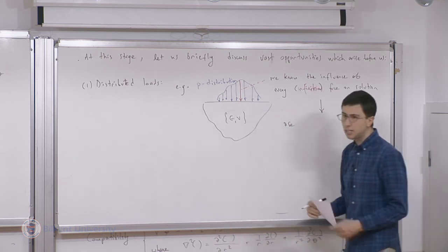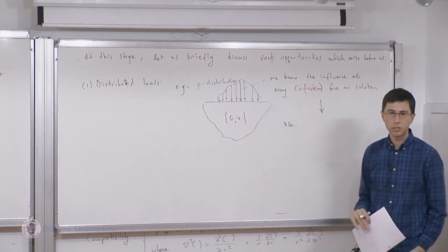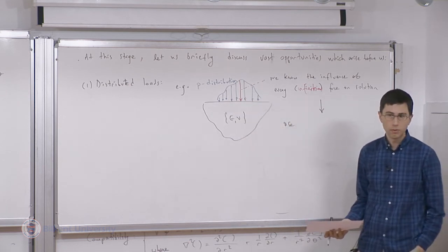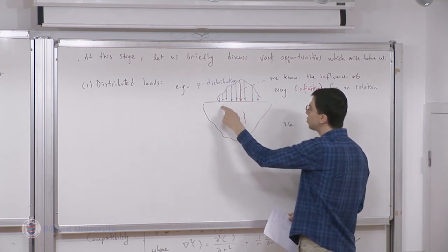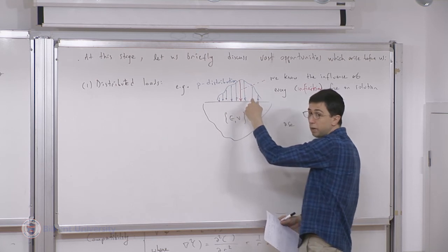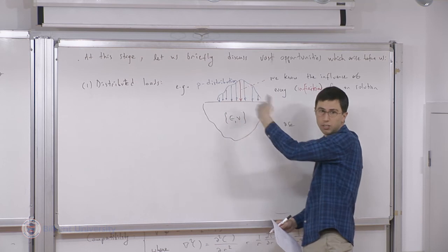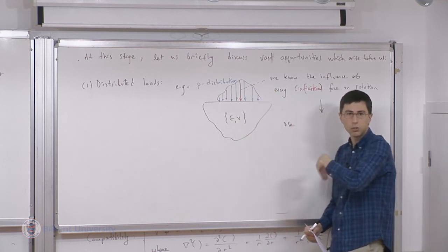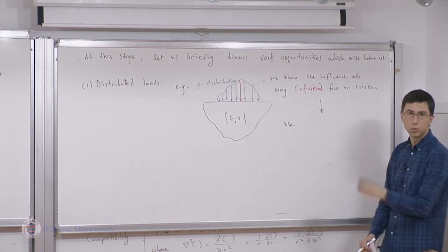So if I seek the solution where all of those forces, all of those arrows, are simultaneously present, I use the principle of superposition. I have to sum up the solution corresponding to every one of the arrows, but I have an infinitesimal set of forces. It's a distribution, so it's not a sum, but really an integral. If I integrate the solution distribution, then I get the solution for this problem.